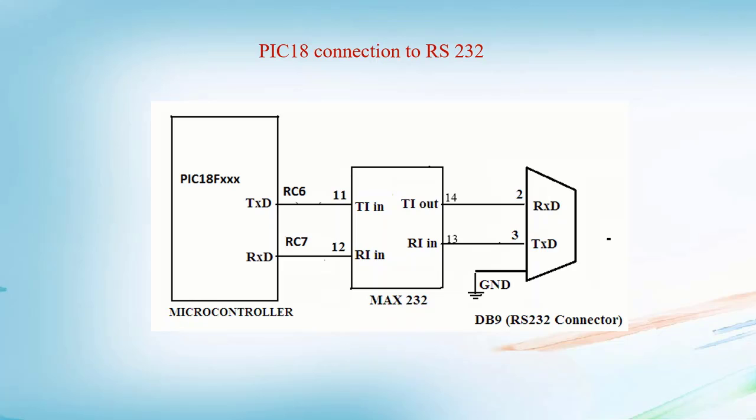These pins are TTL compatible, so they require a line driver to make them RS232 compatible, because the PIC18 or microcontroller knows the TTL logic level and RS232 doesn't know the TTL logic. Therefore we require a line driver to make them RS232 compatible. One such line driver is the MAX232 chip.